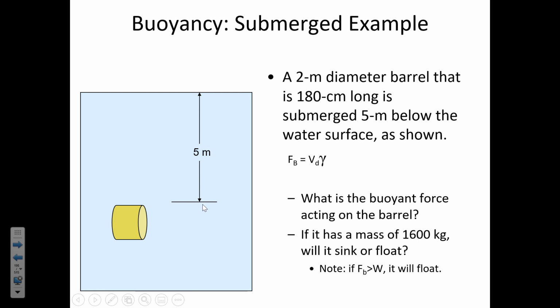No, you're right. Why not? Why doesn't the buoyant force change based on how deep it is? It's only based off of the volume and unit weight. And so neither of these things change based on depth. The unit weight is constant.